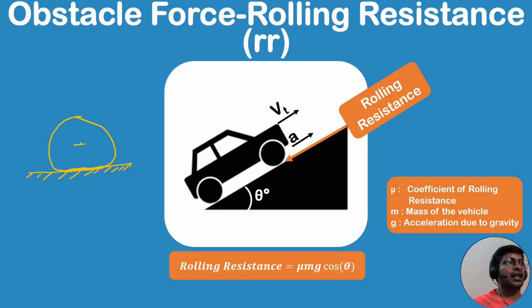So let's say a tire is rotating with respect to this center, and the motor is trying to move this tire in a forward direction. So we get some sort of intuition that this point is going to get some sort of obstacle force in this direction, and because of this the motor has to provide some extra effort, and that extra effort is equivalently described at the vehicle level as a rolling resistance force towards the back of the vehicle.